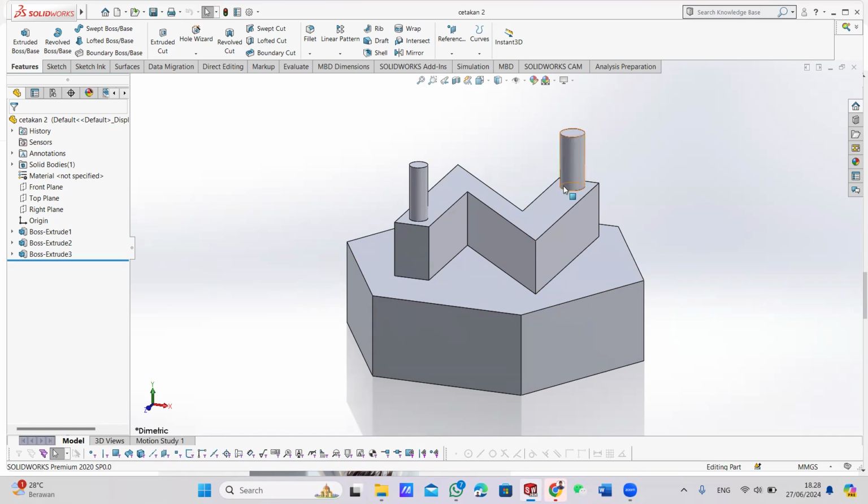The riser's function is as an empty space so that more molten metal can be poured into the mold, because there will be shrinkage when molten metals freeze. So you need a riser in your material design for simulation. So I have the ingate, I have my main material, and also I have a riser. So let's start designing our products.